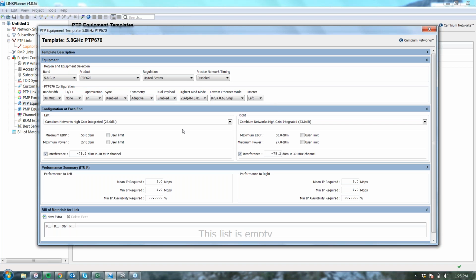They are capable of transmitting 2 separate streams of information across the V and H polarizations. You can cap your highest modulation mode. I generally like leaving it at the highest possible modulation mode so that adaptive modulation can vary down to the lowest Ethernet mode and up to the highest mode.